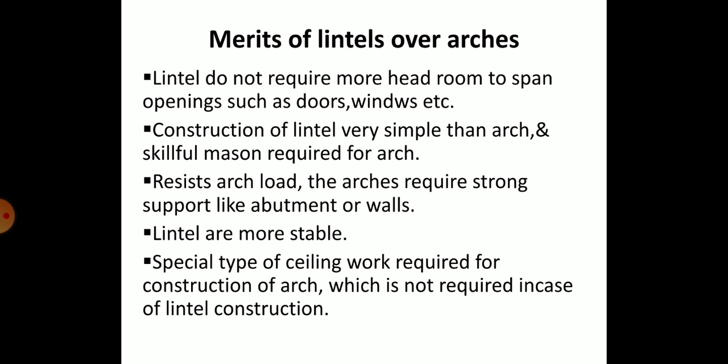The next part is the merits of lintels over arches. So what are the merits of the lintels? The lintels do not require more headroom, but arches require more headroom to span openings such as doors and windows. The construction of the lintel is simpler than the arch construction, and a skillful mason is needed for arch construction. So that is also one merit of the lintel.